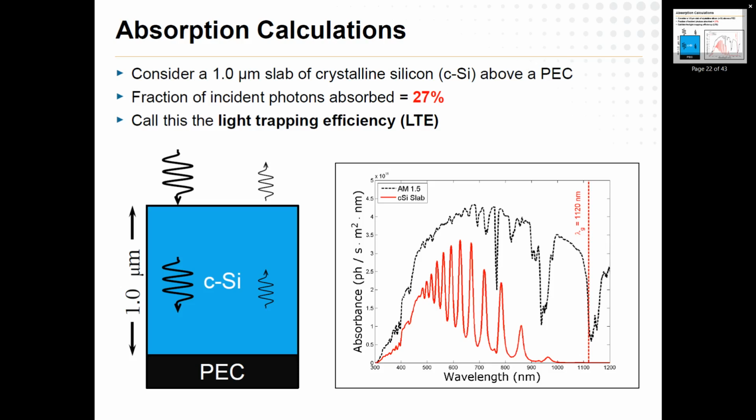That's an interesting phenomenon, because depending on the wavelength and the thickness, that down and back might actually destructively interfere with that initial reflection. And you get this weird resonance effect, where you can destructively interfere all of that reflection at once, and all your light gets trapped. So you notice these little peaks and valleys here, where at this wavelength it's doing very well. But then you go off that resonance a little bit, and all of a sudden the opposite happens, where this reflection will now constructively interfere, and you get even more reflection. That's called Fabry-Perot resonance, and that's what you see in this spectrum here.